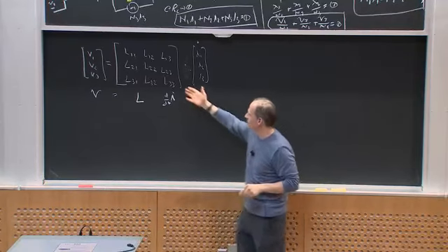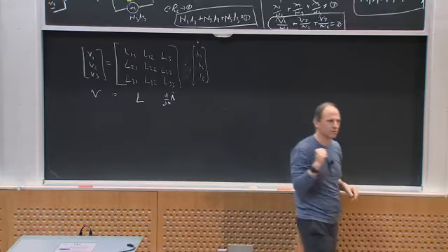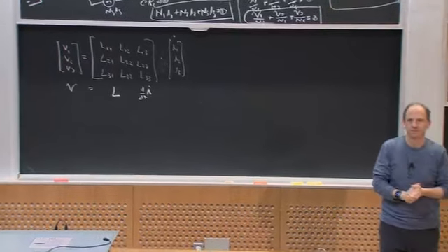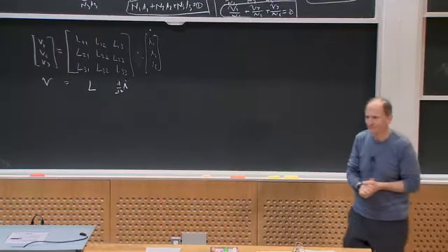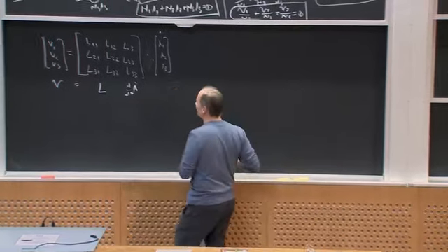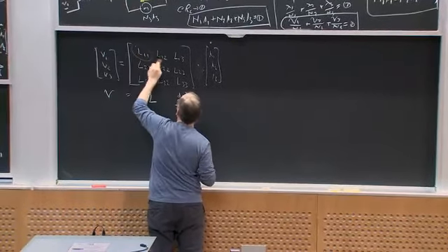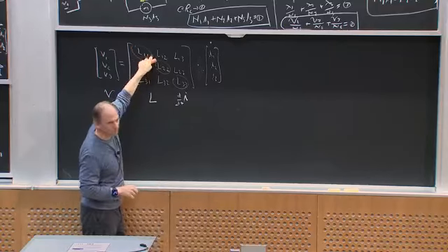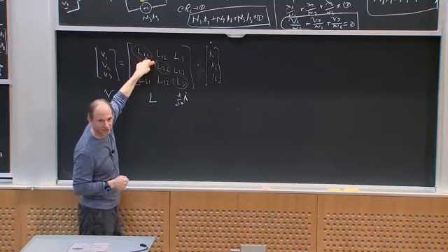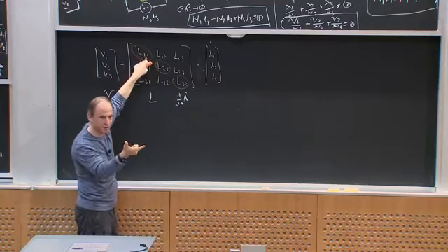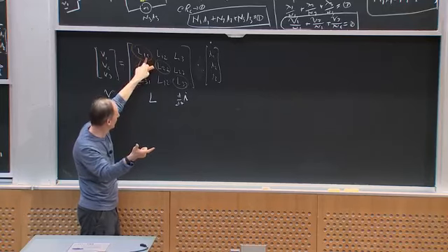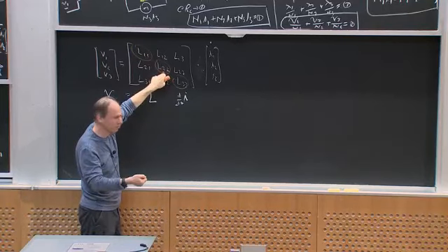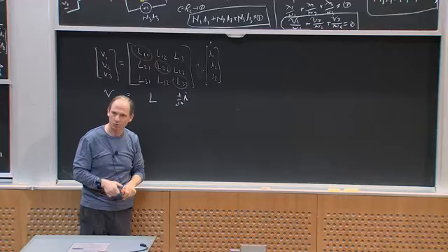How many independent parameters do I have in this structure? 6, yes. I have my 3 self-inductances. Each self-inductance is the inductance at a port with nothing else connected, measured like an inductor from one port with everything else open circuited. I get L11, same thing for measuring L22, and the same for port 3.